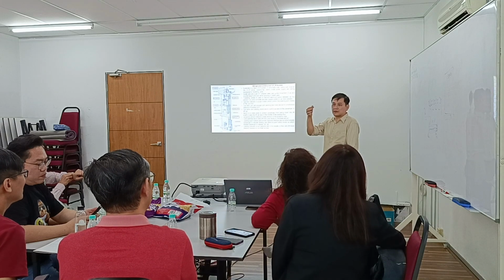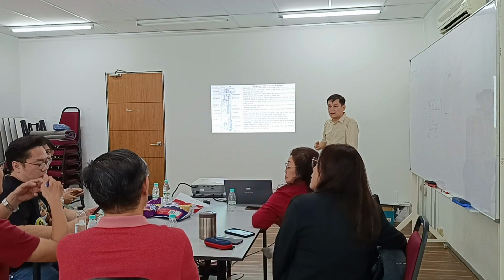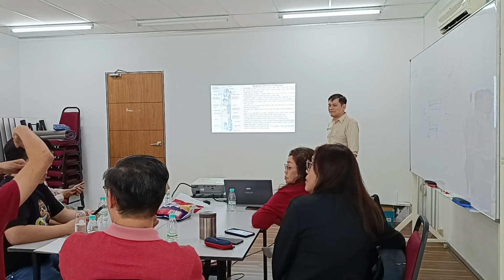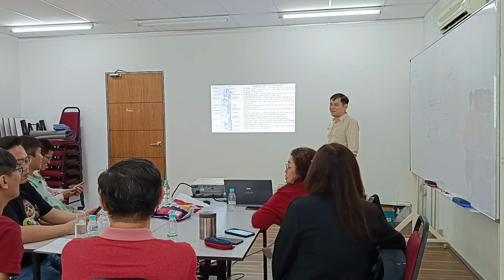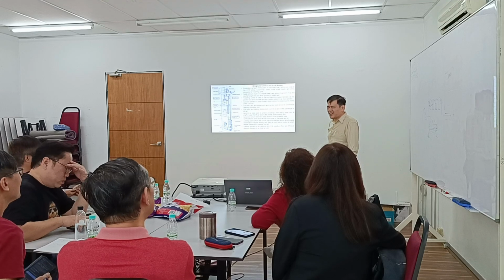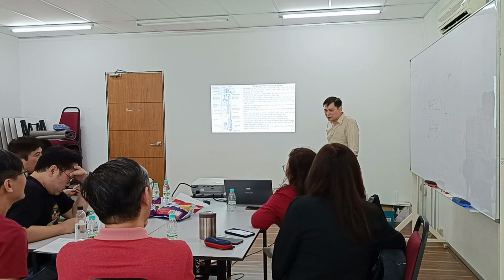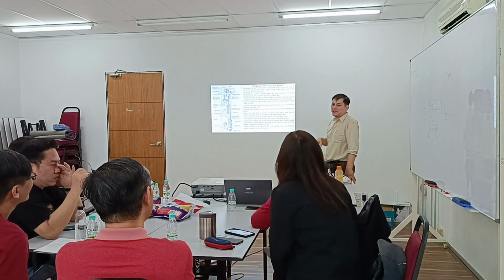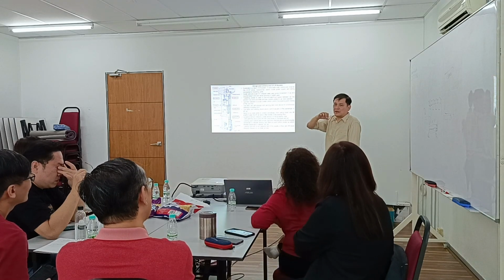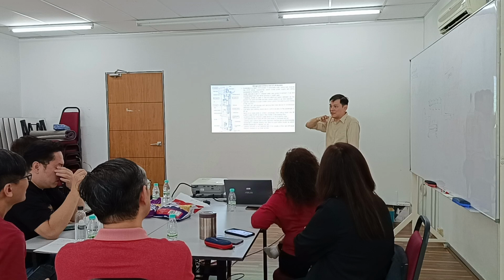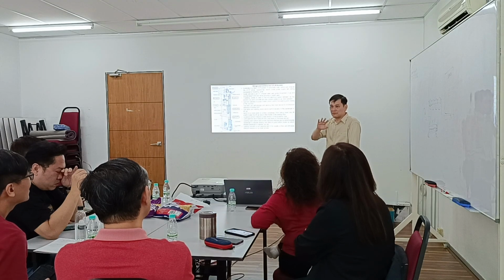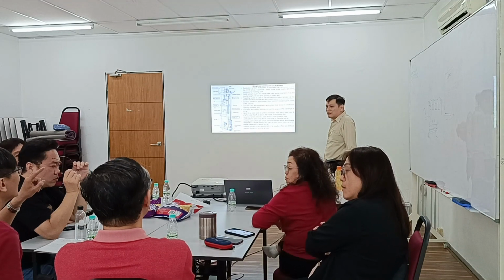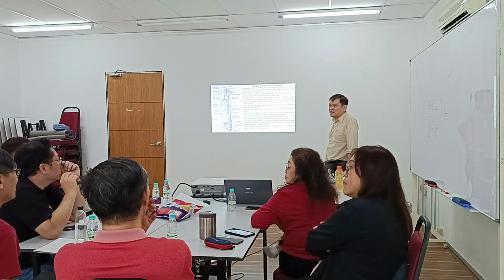If let's say they have dusty marks, every month they will put oil on it. No, cannot. The rope then gets oil. Actually, that is the wrong approach to apply oil onto the rope. You will slip. Because actually, inside the core, they already have lubricant. Technically, we should not apply any oil or any chemical. The reason typically is rust. Rusty ropes have to be changed, no choice. Within 5 years, a new one.